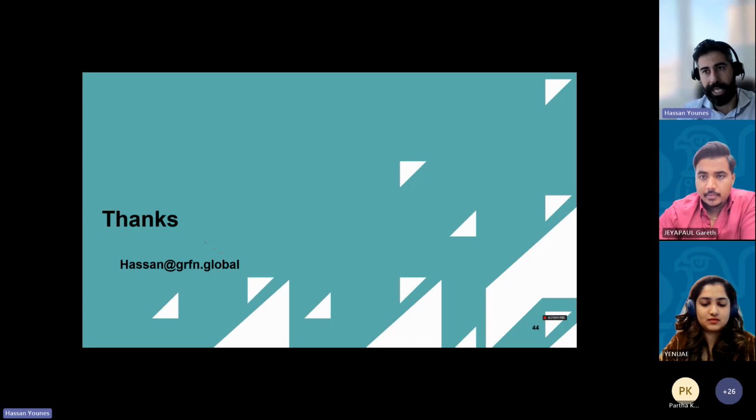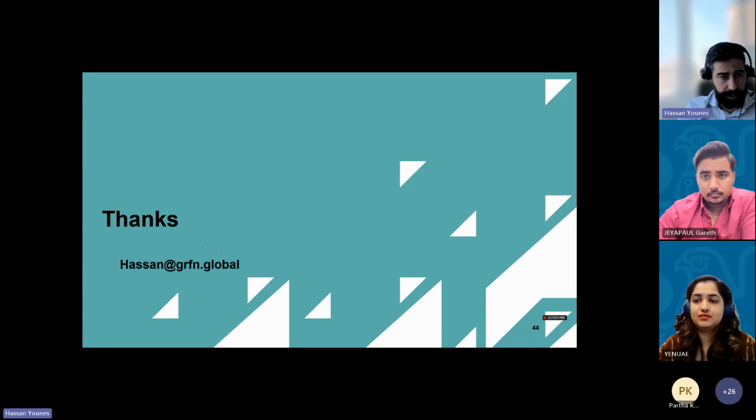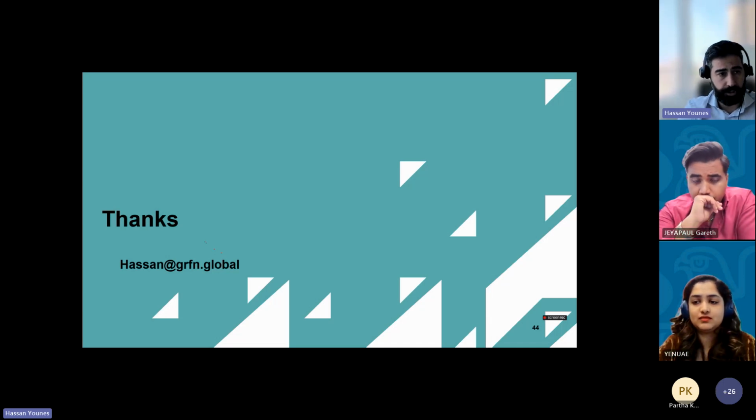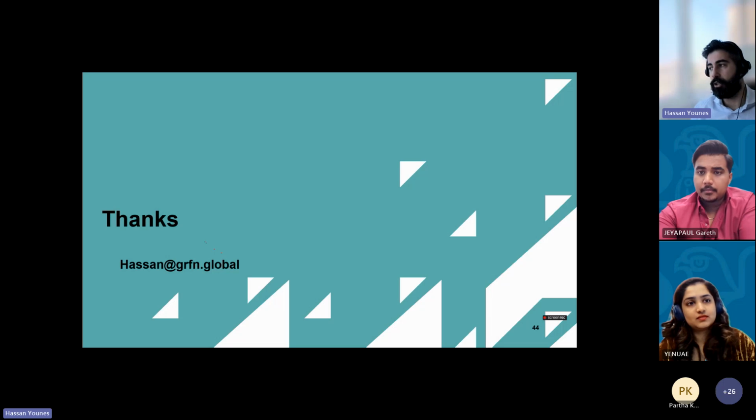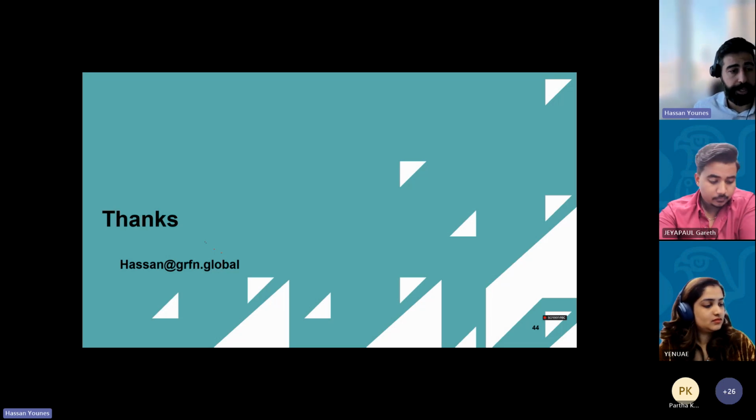But if you want to do a full calibrated model, then the only way is to get to site, get the nameplates, do some measurements, whether it's spot measurements for equipment that just runs at a constant speed, and you need to put in a data analyzer, maybe some flow meters, and collect data for maybe a week at least to get some information on what's going on. If they're chillers, maybe you need to go in summer again to figure out what the peak consumption is if you're doing your audit in winter.